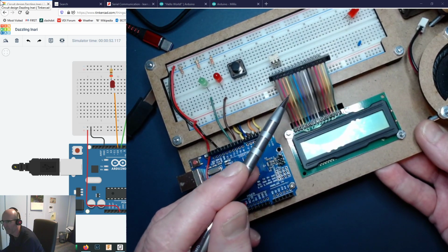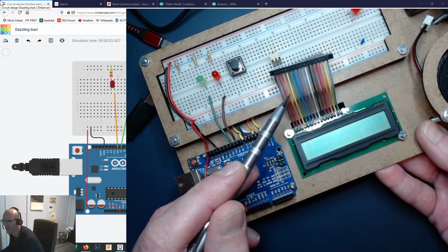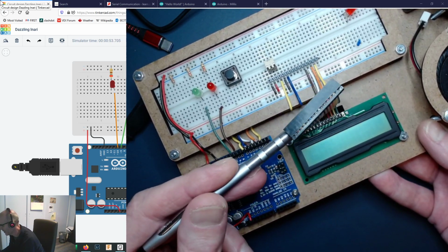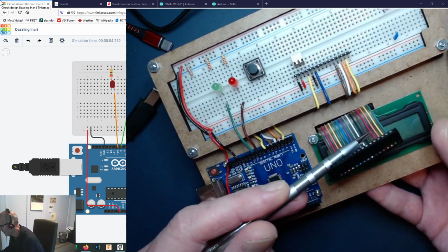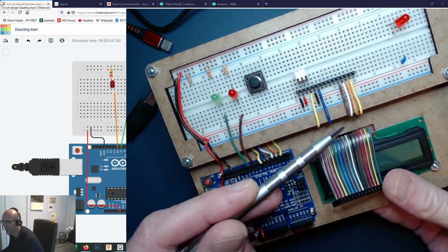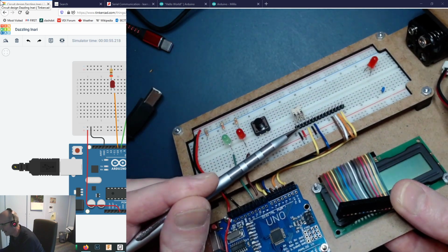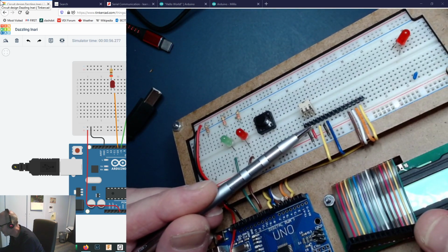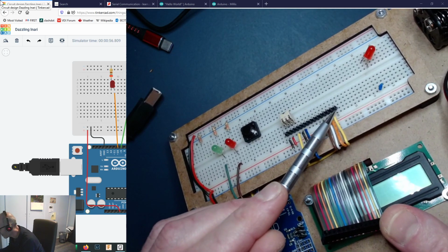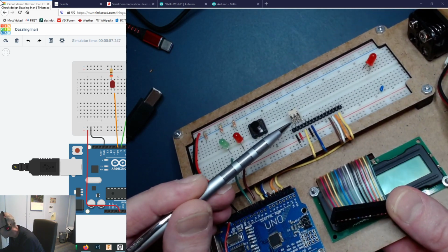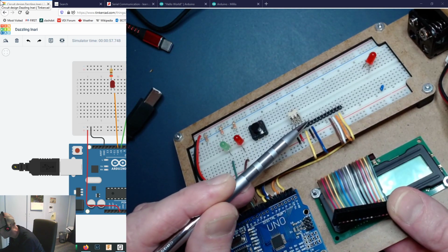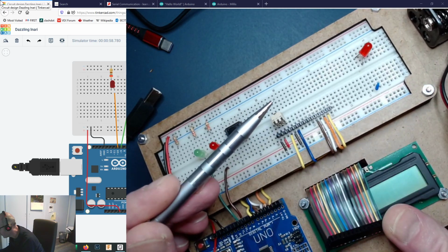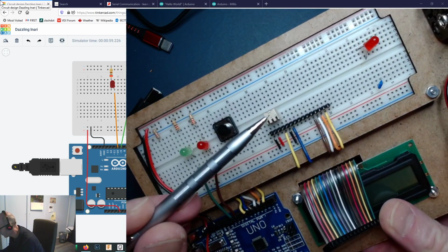When you see this type of cable, there's a pretty good chance that you're dealing with a parallel interface because you've got lots of room for data to be transmitted across there. All right, now in your Big Bad Breadboard board kit, you've got some nice double-ended headers like this that can plug into your board right here, and you can just snap them off to the length that you need. So give it a count. There's 2, 4, 6, 8, 10, 12, 14. There's 15 pins on there that you can use.